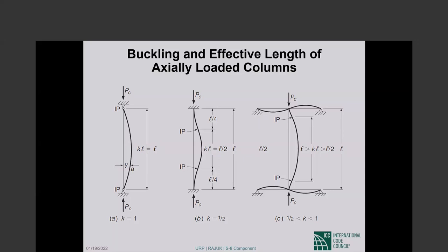Okay. If it is a braced column, typically the ends will be neither fixed nor free. The column will frame into a beam or a slab at both ends, and the beam into which the column frames will provide some restraint that will be between this and that.